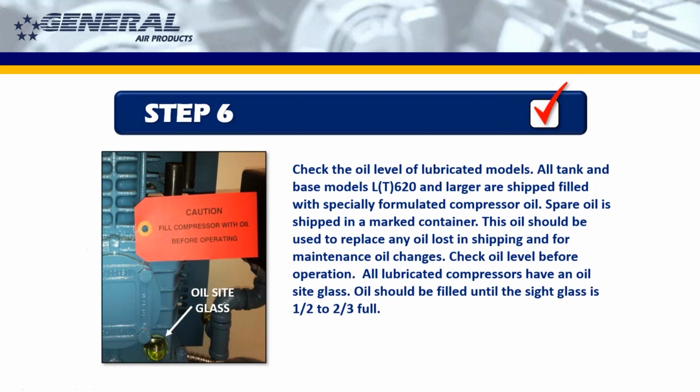Check oil level. Can't tell you that one enough. Check that oil level on the oil sight glass. Should be about half full in all of these sight glasses, or half empty if you're a pessimist that day, but it should be half.